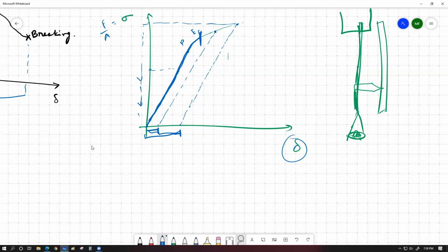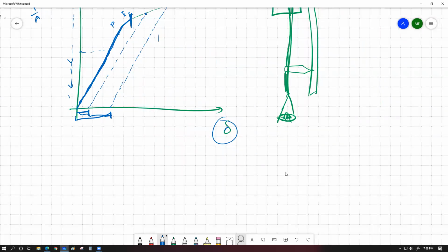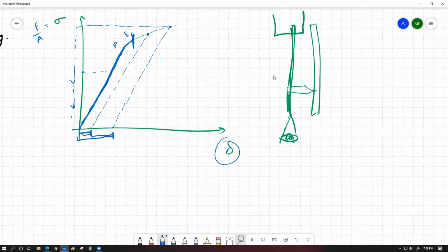How much work is done can be found out by the area covered within this graph. For example, let's say we have a specimen, this one, and we applied load to this object up to this much load. Let me use red for this case. Let's say we stress the specimen up to this point, and then we start to unload the whole specimen. As we unload the specimen, eventually we get to this point on the x-axis, and the object is going to have some permanent deformation.